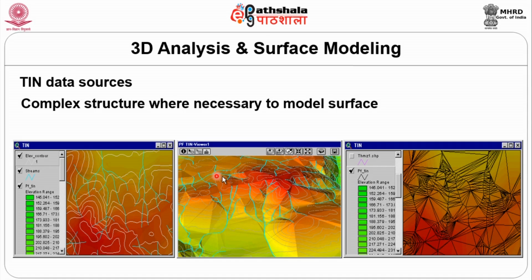How do these water bodies, all these drainages, flow from which direction to another direction? This will be the demarcation, or the points of highest elevation, in a given terrain. For watershed analysis, any kind of study, it need not necessarily be for topographical survey or civil engineering application. For all kinds of studies, what one does is take into consideration the watershed boundary. This is the boundary. We say that all water which is falling on this side will travel to these drainages. All the water which is falling on the other side of this particular ridge or peak point will go to the other side.